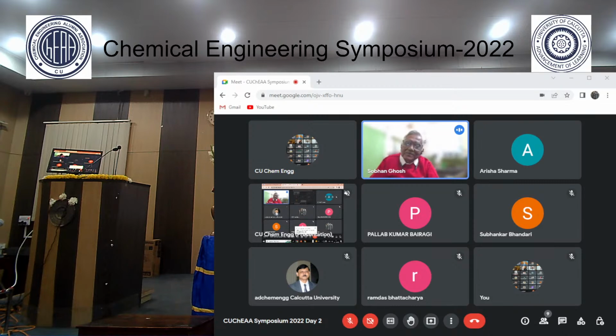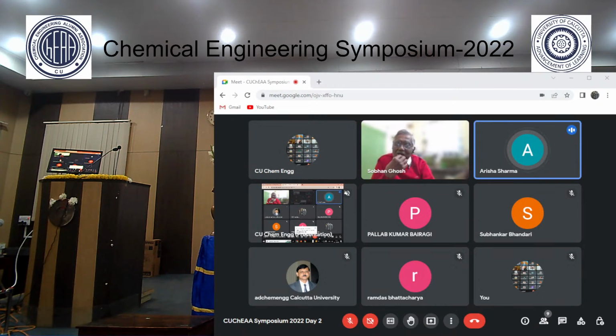Okay. So you haven't answered, please? Yes, sir. We haven't checked the steam to carbon ratio yet, but for the question around the nitrogen, right now we are just focusing on it as an inert gas. So we are not taking into consideration what you were saying about the NOx formation. We have not taken that into consideration.